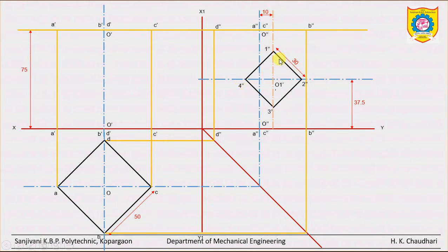Now by taking the projections in the front view and top view, just produce the views of this horizontal prism. So first of all, just extend this horizontal center line. It will become the axis in the front view, and the length of the axis is 90 mm.